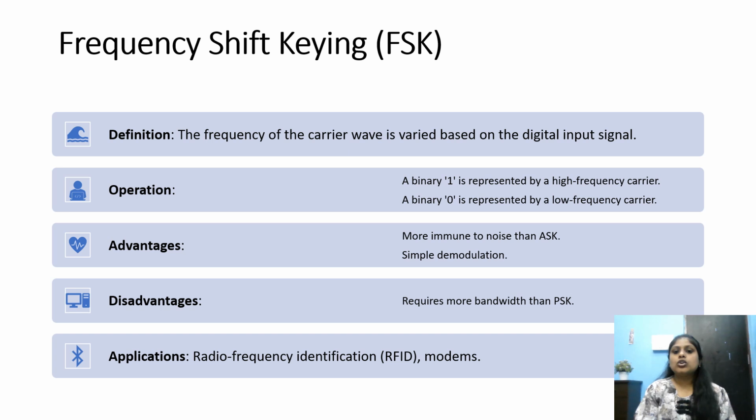Advantages: more immune to noise than ASK, simple demodulation. Demodulation is what brings back the original signal. Disadvantages: requires more bandwidth than PSK. Application: radio frequency identification, that is RFID, and modems.